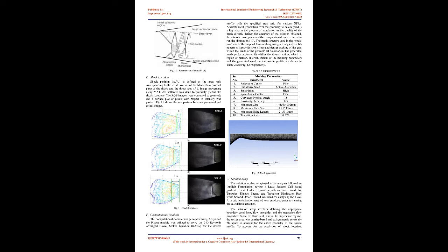The subsonic flow in region 2 tries to achieve a uniform pressure gradient by developing back pressure such that the strength of the shock decreases near the axis and increases whilst moving away from the axis. This can be achieved by moving the shock downstream, to reduce shock strength near the axis, and upstream, to increase shock strength moving away from the axis, respectively. In doing so, the shock structure attains a convex shape at BC and the separation shock NDC becomes more oblique in nature. The presence of a positive pressure gradient implies an increase in pressure from axis towards wall, and in this case the shock movement will be opposite and the Mach disk attains a concave shape. This type of shock structure mostly happens in thrust-optimized contoured rocket nozzles.